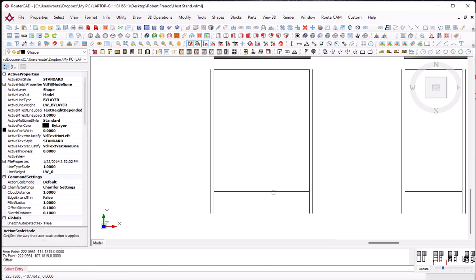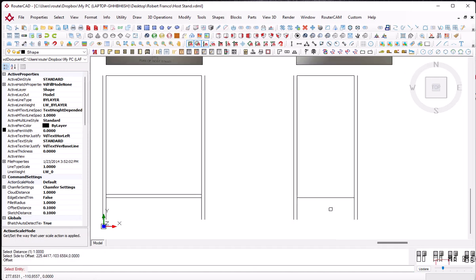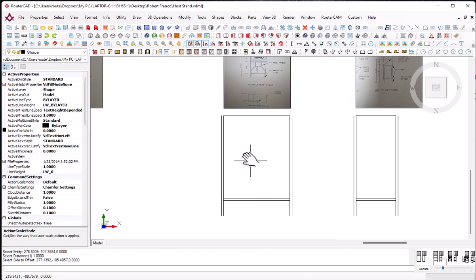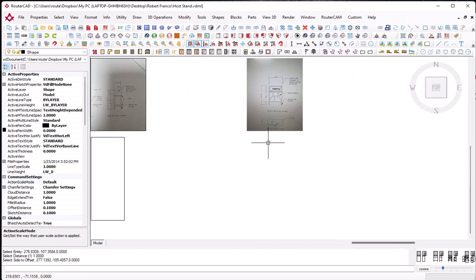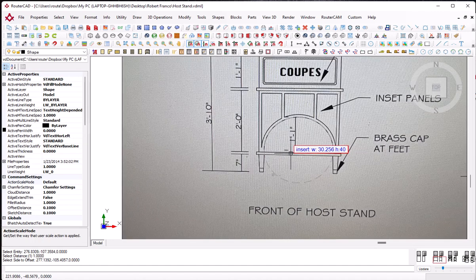And I'm going to select the line, right click to accept 1 inch and just offset 1 inch. I'm going to do the same thing here. I'm just going to right click, select it, and move it up 1 inch. So there's your 2 offsets. Now looking back at the drawing again, they want 20 inches in between this next set of lines.